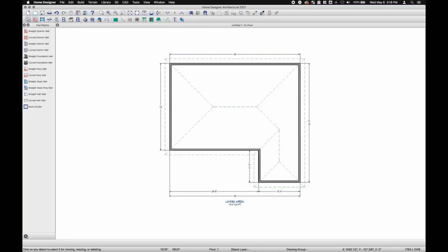So far, I've talked about setting wall lengths, but what about wall heights? Instead of thinking of individual wall heights, Home Designer thinks in terms of ceiling heights for the rooms. What I mean by that is if I click in the middle of this room, notice it highlights and I have the Open Object button on my Edit toolbar. I've selected the room object.